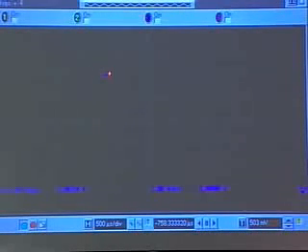So I'm increasing Vi. Notice that initially the dependent current source is off, so I move straight down. Nothing happens until I hit a value at which the current source begins to come on, and then I begin to see a drop in the output as the current source begins to conduct current.